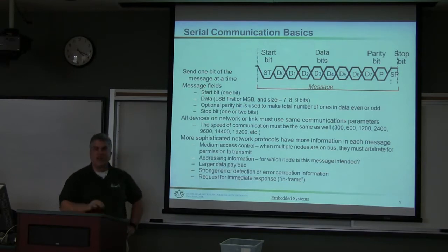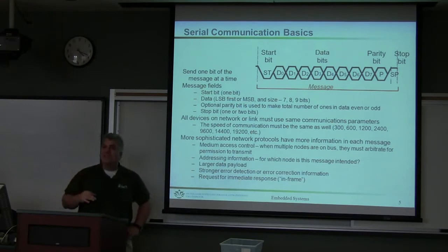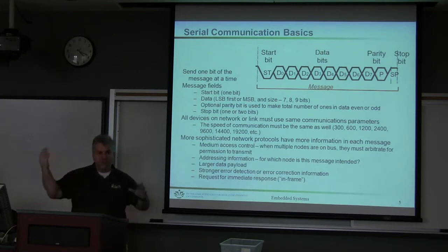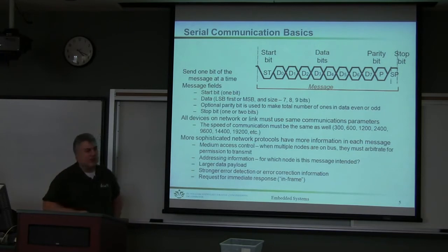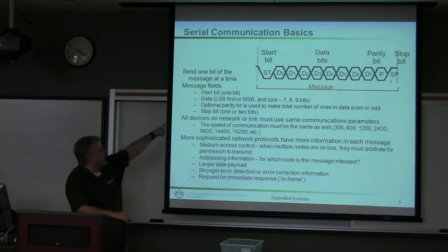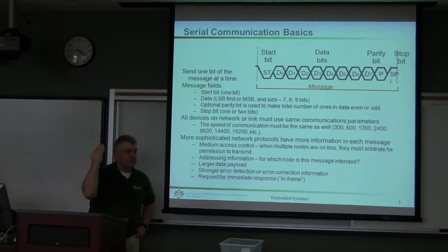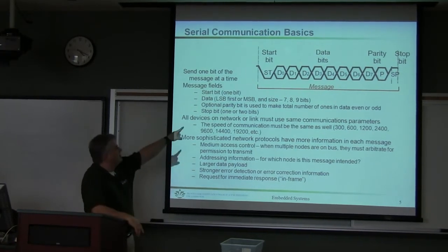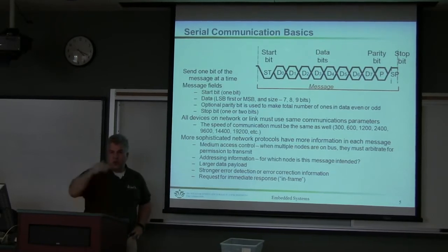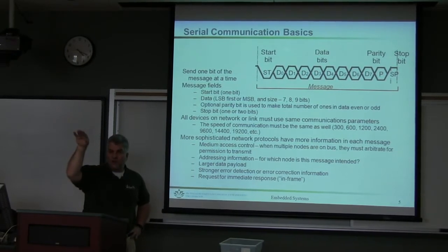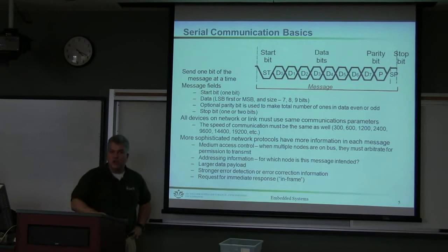So the reason you send asynchronously and set your expectations that way is because you have two different devices running at two different clocks. And how do you do that? Well, you have a start bit. When one machine is going to send something, it sends a start bit, which lowers its signal from a logic high to a logic low.